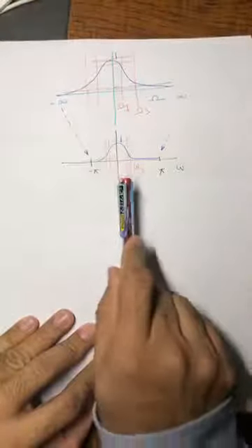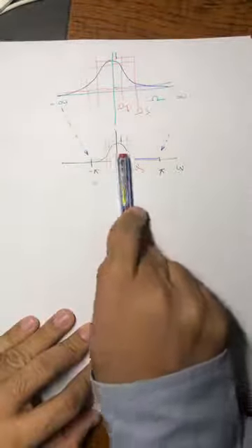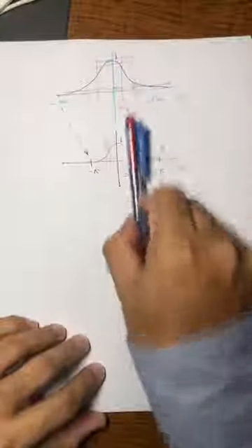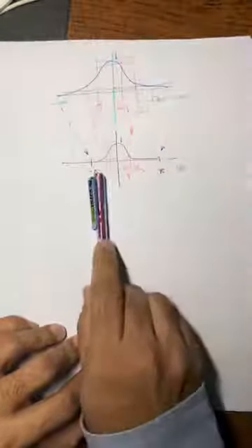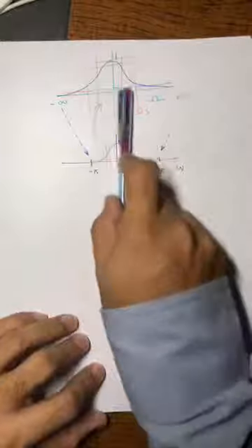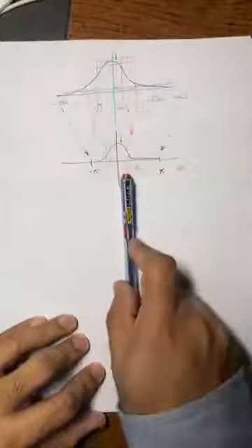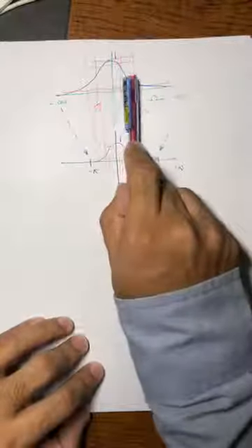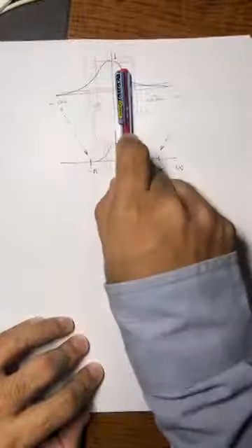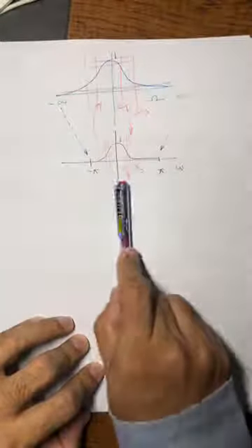And another reason is, now this omega p maps to capital omega p, this omega stop maps to capital omega stop. So first I have these specifications, I convert them into analog specifications by expanding them in frequency, and then I come back to this. Because of this reason, I know that I have to change my specifications to capital omega, and then I need to change back. So I'm using the same transformation. So it will guarantee that if I'm meeting my specs here, I'll meet my specs here, because from here I transform my specs to analog.